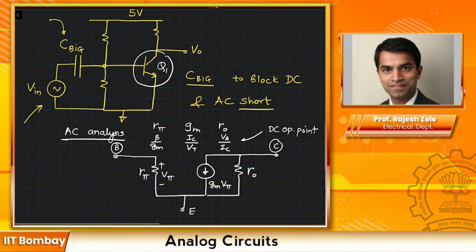As I said, the resistor, let's call this R3, is connected from output to 5 volts, and 5 volts we are going to connect to ground for the purpose of the AC analysis. So here in this case it would go from collector to ground. This would be R3, 1.33K. The resistor R1 and R2, which were 80K and 20K.